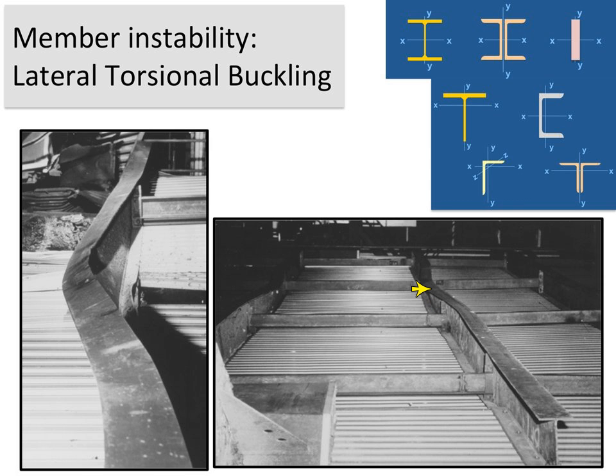As a result, the top flange is all in compression. There's nothing bracing it. And we got this mode like I was showing you in a cartoon in the previous slide, but this is an actual real beam now in a mode of lateral torsional buckling.